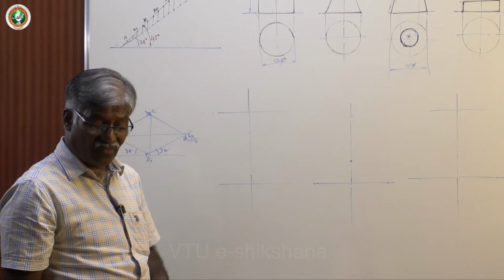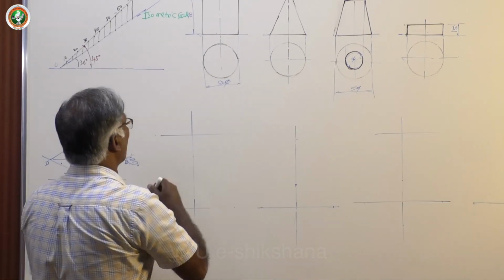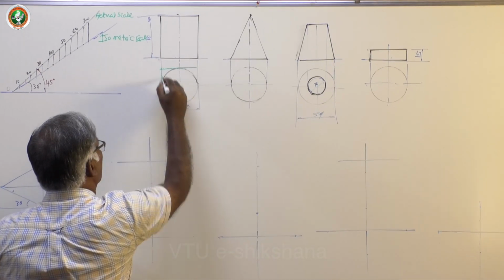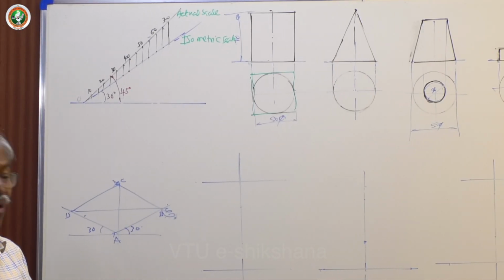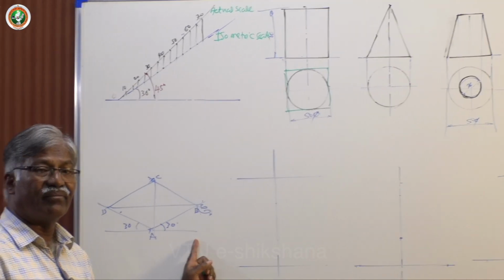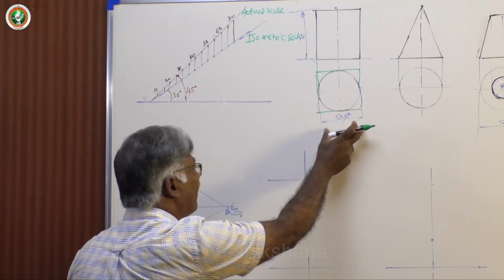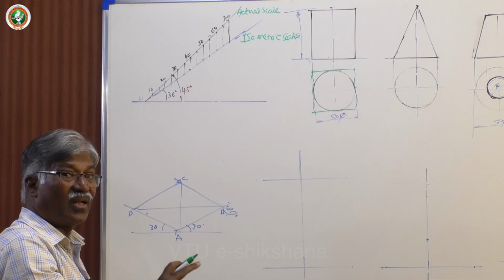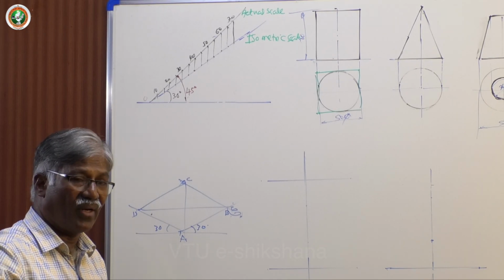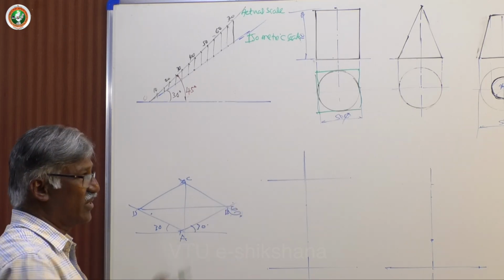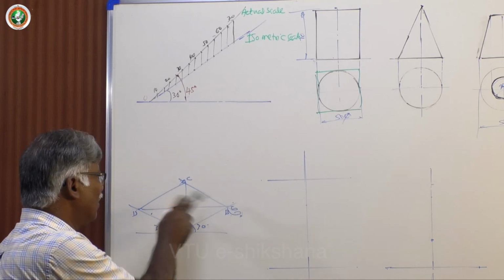Whenever you get a circular surface other than rectangle and square, you have to enclose it in a box. So assume that I enclose this in a box. I will get a square. You have to draw the isometric projection of a square. You know how to draw isometric projection of a square. So you have to keep either side 30 degree and take 50 mm isometric draw if you are very particular about isometric. Now onwards let us say it's isometric view only, for easy understanding and also easy processing of teaching. See, I take 50-50 and also this one.